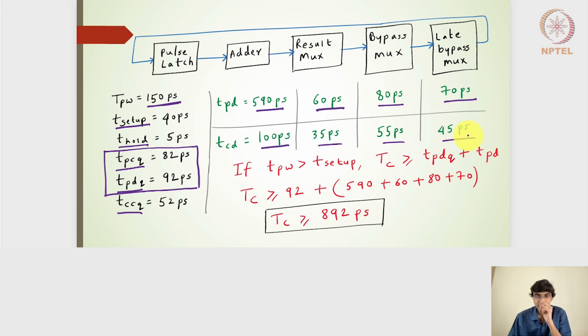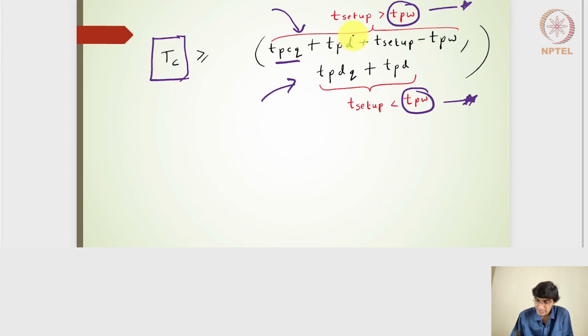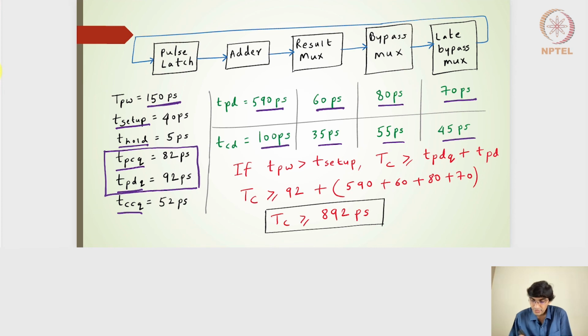We have looked into the maximum delay constraint, so we will apply it here. In the last two slides, what we saw is the maximum delay constraint. It gives us the expression for the TPD in both configurations, whether the TPW is low or high. So TPD will always help in determining the maximum delay constraints. Moving ahead, for these expressions, can we identify the minimum clock time period, or the minimum pulse time period, so as to have no setup time failures in this case?